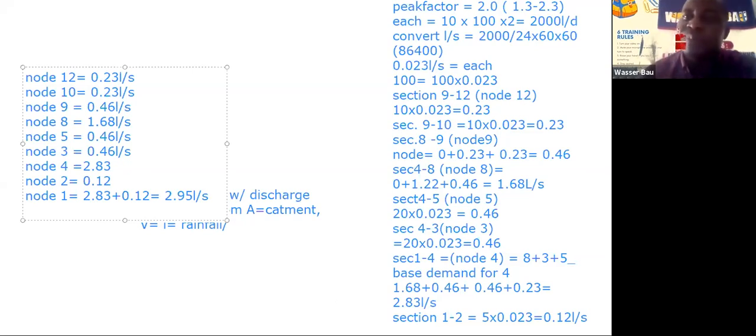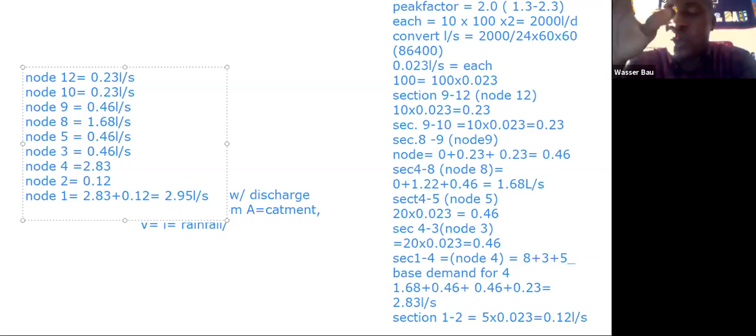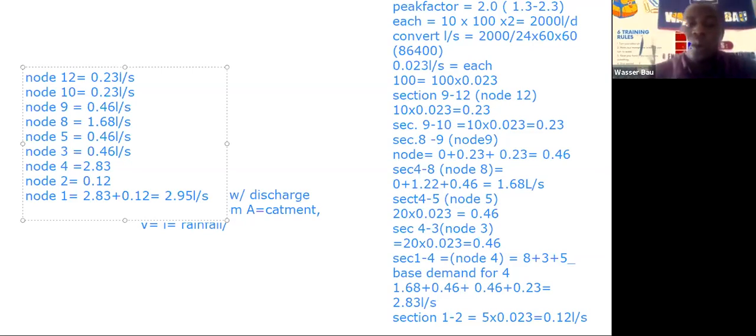So let's start with pipe 1, pipe ST to 1, which is the first pipe, the main pipe, the primary pipe. That's about 2.9, so that 2.9 is almost 3. Let's assume that the slope, I don't want us to go to the question, let's assume a slope of 0.1%, which is 1. So what I now do here is I'll come to 3. This is my 3. I'll read it off and then hit it against 1. Against 1 is perfectly in between 2 pipes.